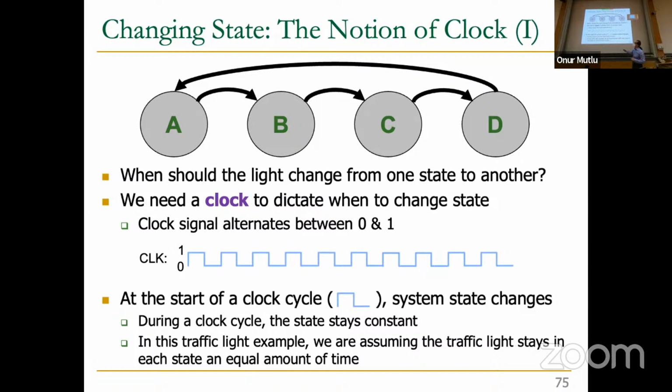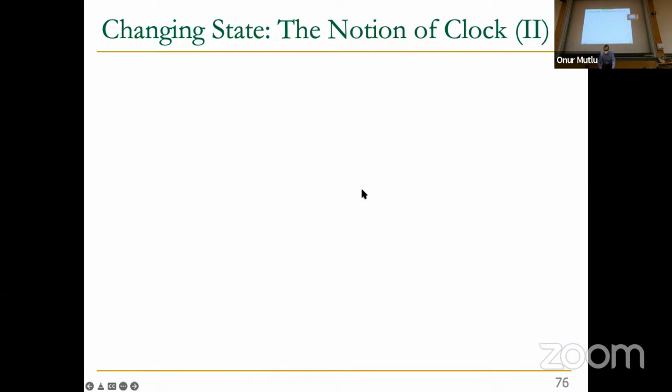Now you stay 20 seconds. And then next clock cycle, you go to B. That's how you can stay 20 seconds when the light is green. Right? You replicate the A state so that you stay in a replica of the A state 4 clock cycles. Makes sense, right? So basically, you can use the notion of time and change the state machine so that you can stay in a particular state different number of cycles and different amounts of time in the end. So it's beautiful.